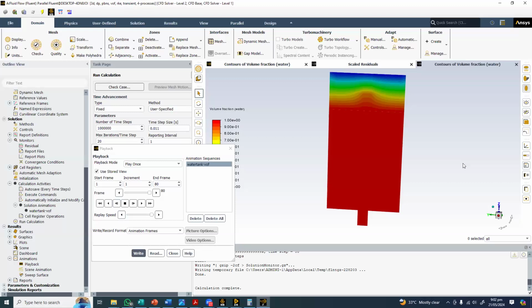You're correct actually that we should have the sharp interface, especially here. Because we have a very coarse mesh, that's why we have this problem occurring here. But if we go with the fine mesh, then the time step size will also be reduced, because we have to keep the Courant number less than two, maximum should be two, not more than two.